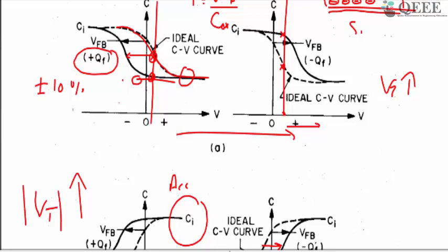It's the same thing with optical excitation. If you shine light and measure the capacitance, your photons are generating electron-hole pairs. So that is very important: if you are trying to measure any MOS capacitor, make sure that the temperature of the chuck is at room temperature and there is no ambient light falling on the MOS capacitor, otherwise it is going to shift your capacitance-voltage characteristics.